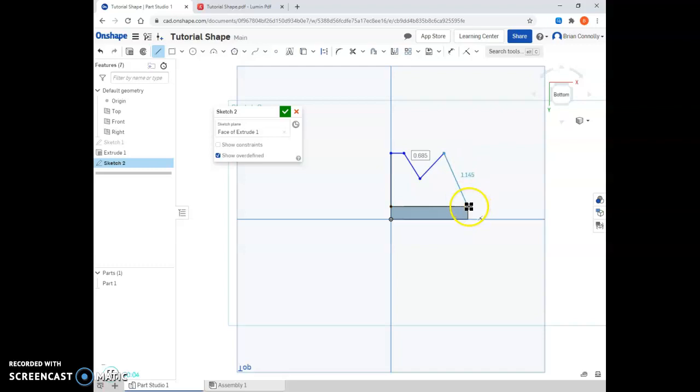Sometimes I want this to actually line up with this corner as well, so I can move my mouse down and line it up. So now it's not only horizontal, it's vertical from that point. So I can click there, and then click there, and you can see that edge already existed, so I didn't need to create that. It turned into this gray shape right here.